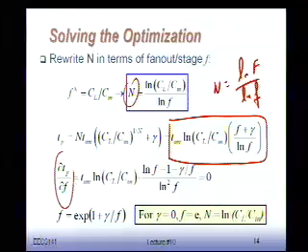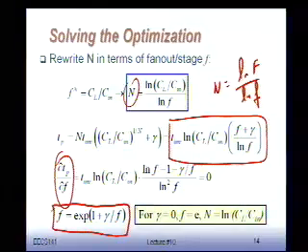We take our propagation delay and take the derivative with respect to small f. I already assumed that all stages have the same fan-out, that this is going to be part of my optimal solution. So I take that whole derivative and play around with it, and I get this kind of nasty expression. And actually, the answer is shown right here.